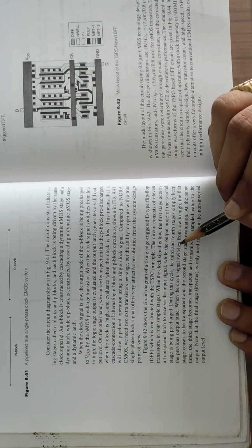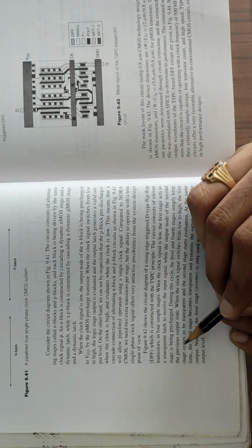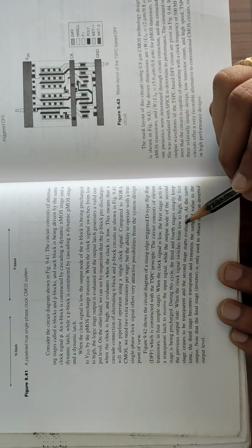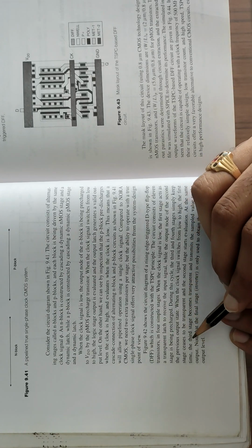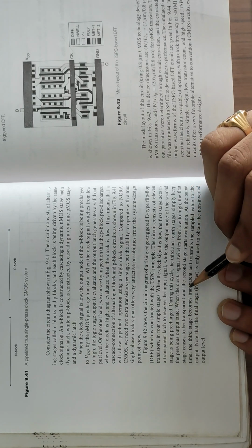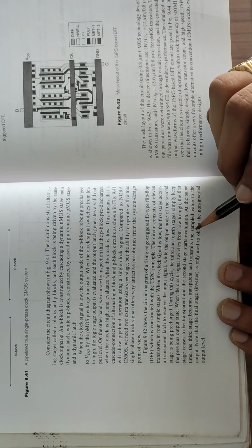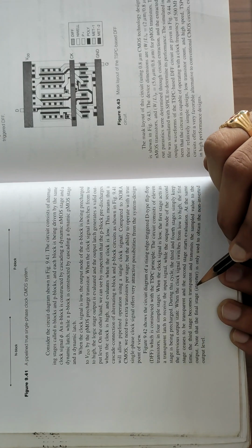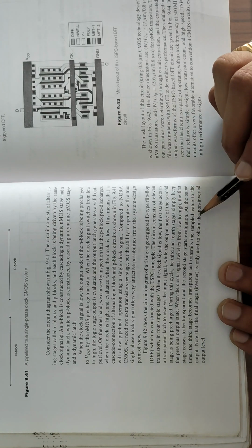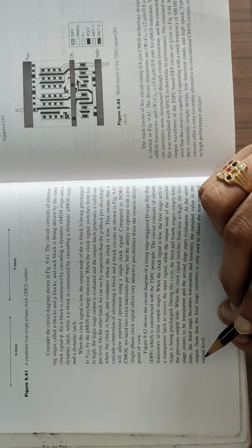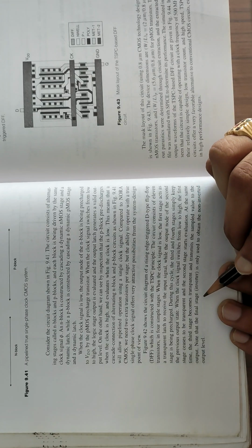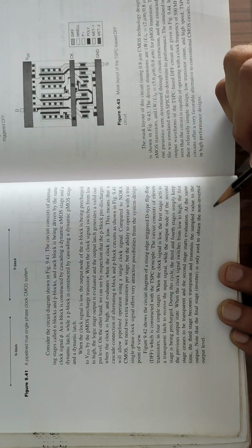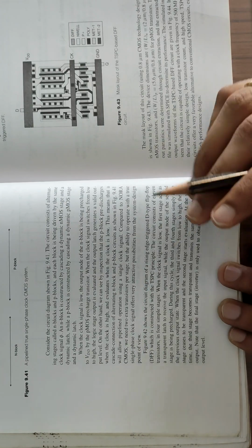During this cycle, the third and fourth stages simply keep the previous output state. When the clock signal switches from low to high, the first stage ceases to be transparent and the second stage starts evaluation. At the same time, the third stage becomes transparent and transmits the sampled value to the output. Note that the final stage inverter is only used to obtain the non-inverted output level.